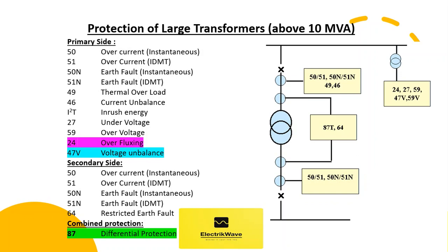It should be noted that a differential relay should trip only for an internal fault. A differential relay should never trip for an external or through fault. For this reason, a percentage biased relay with dual slope facility will be the best choice. This will have very good through fault stability.